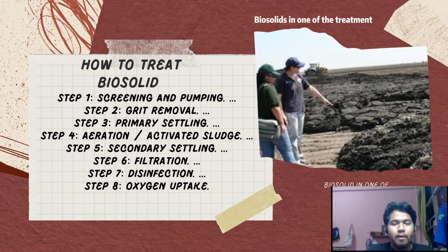Number 7. To ensure the treated wastewater is virtually free of bacteria, ultraviolet disinfection is used after the filtration step. The ultraviolet treatment process kills remaining bacteria to levels within our discharge permit. Lastly, the treated wastewater passes through the effluent outfall where it joins the river.